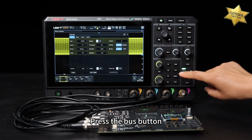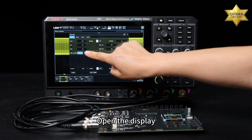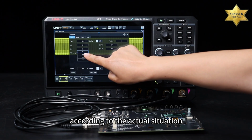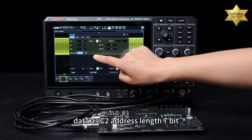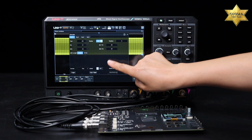Press the bus button. Select the type of bus 1 as I2C. Open the display. Select clock and data source according to the actual situation. Here we choose clock as C1, data as C2, address length 7-bit. Click on trigger below.